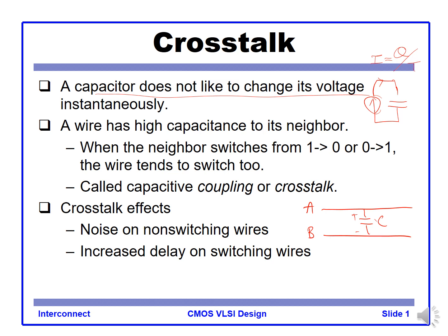So in this kind of two-line structure, if one of the lines moves, like the voltage from 0 to 1 volt, then the voltage across the capacitor is like to be 0. So line B will follow the line A activity like that, and then eventually goes down by the certain driving impedance there. So momentarily, line B follows the activity of line A, right?